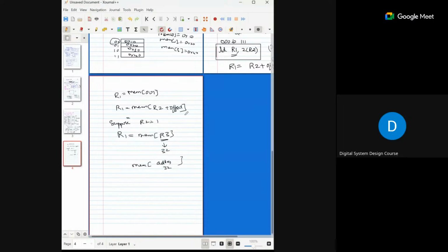For simplicity, we have taken only 3 bits of address line. It means that in a regular RISC-V architecture or any ARM-based architecture, the address line is about 32 bits long. So I have a memory of 2 power 32 locations. Please excuse this particular part, because for simplicity I adjusted it to a 3-bit address, but all other operations remain the same.